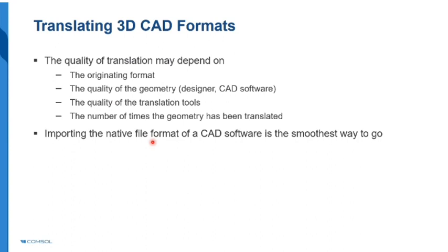For example, if you want to work on any 3D solid modeling, then do not import any STL type of file, which is just a shell file, and do not try to create a 3D object out of that. Though it is possible to create such 3D thick objects from that, the quality of that CAD will be very poor. If you are working on shells, then definitely the STL file format will be appropriate. But if you need to work on 3D solid modeling only, then rather than using STL format, use any other Parasolid format like a STEP file.